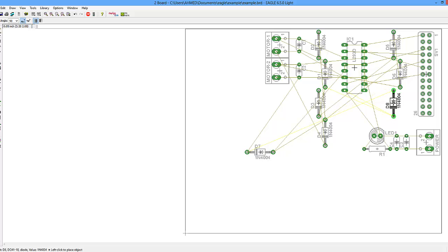So I'll say this one is here, take this a little bit down, this one down. You can actually inch components around. Right now I'm moving it with the mouse and it's moving according to the scale that is allowed on the board. If you want to be more accurate, just press the Alt key and it will move in more precision for you. So I think that's enough.